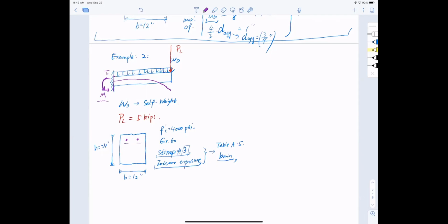Okay, folks, you probably have seen this from your sorority or fraternity houses. I will ask you, if you have a cantilever beam like this, draw me the reinforcement configuration at the end of the design, where A is at. Where does it go? Since it's a negative bending moment, it's going to be on top. Don't mess it up, please. All righty. Okay, so hard question all over.